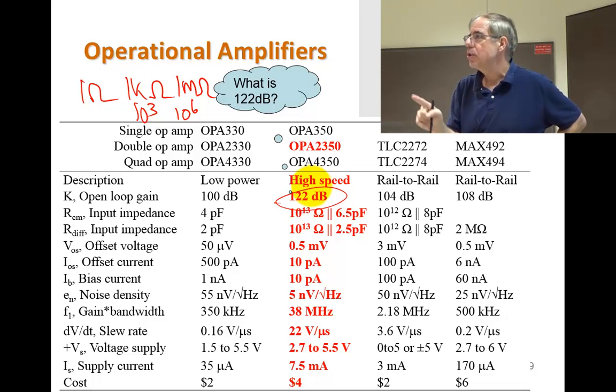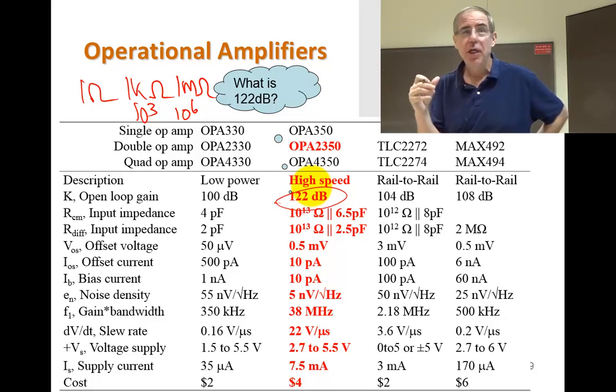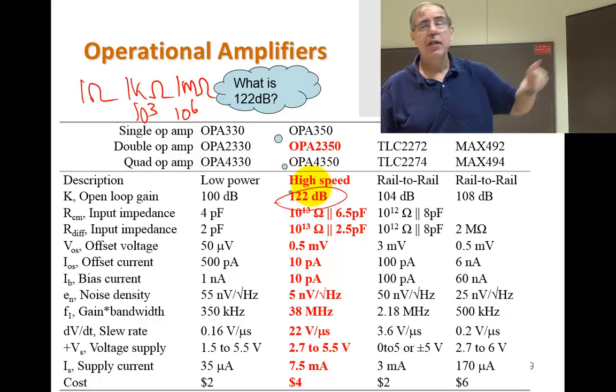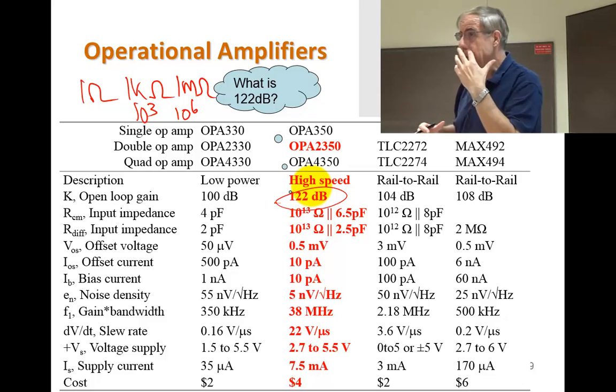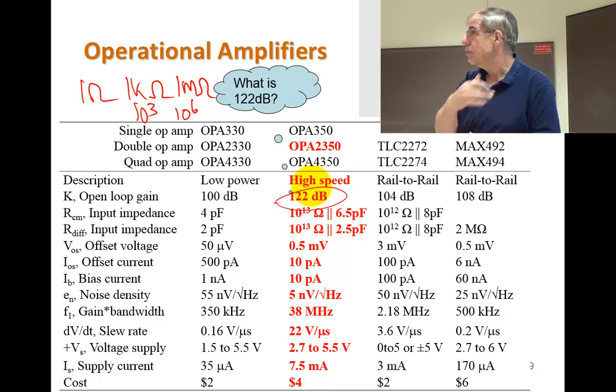Offset voltage causes an offset at the output equal to the offset parameter times the gain of the circuit. The second question I would ask you is, how do you reduce the offset error? It has to do with the columns.